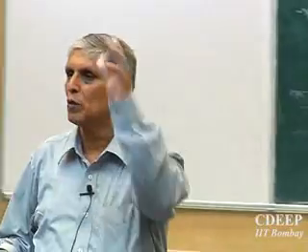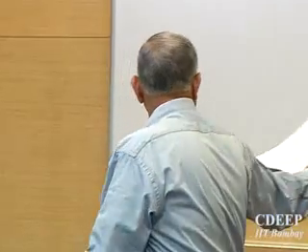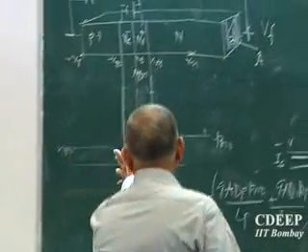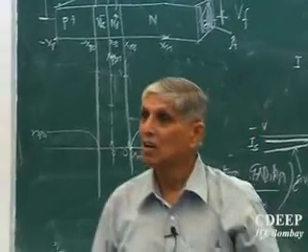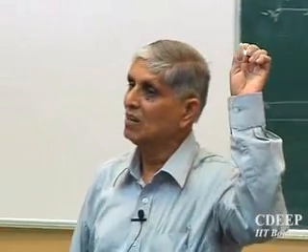If I do the same analysis with the same excess carrier profiles as I did there, repeat for a reverse bias, evaluate charges there, divide by tau, find out the net current there, and you will be surprised. And then why V doesn't come there: e to the power minus VR is much smaller than 1, so the minus sign is taken care of. So you will get this current which is the saturation current in reverse bias. Derived from which equations now? For this case, is that correct? For this case, but it happens to come same as what I got in the case of forward bias.